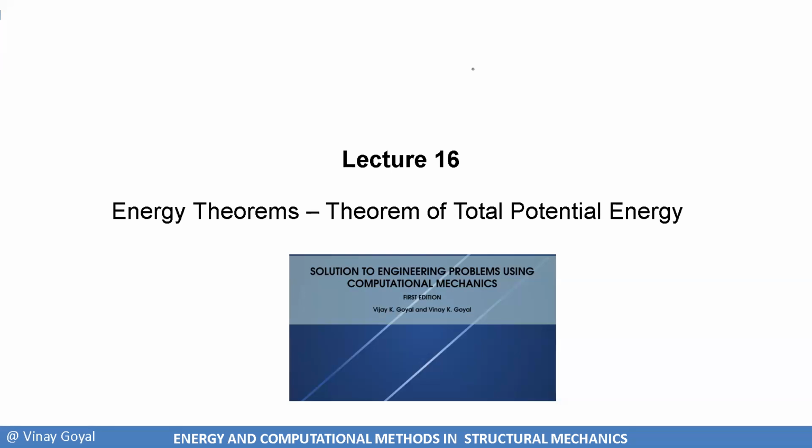Not only that, I was able to come up with Cauchy's relationship, which I had to use a tetrahedron element before to derive. And from there, which is the most accurate theory you can ever have, I then studied simplifications. I looked at the axial bar.